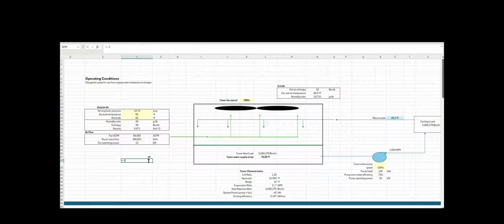And so if we take 0.5 times that, 6.5, the rule of thumb says that our approach to wet bulb should go from 7 to 7 plus 6.5, so about 13.5. We actually achieved 10.5 approach, so the rule of thumb is a little bit conservative. Looks like we can do better if we actually model it. But that was kind of a side tangent. Don't worry about that. Let's look now if we were to change our fan speed. We already talked about that down below.